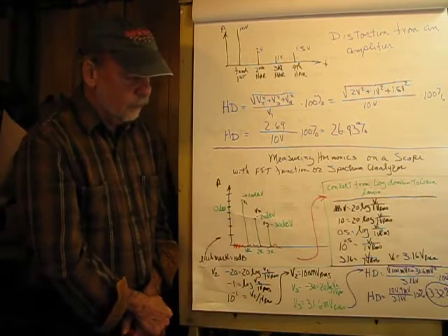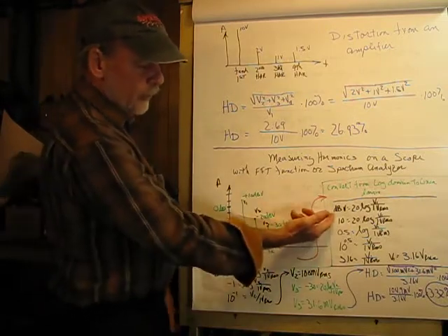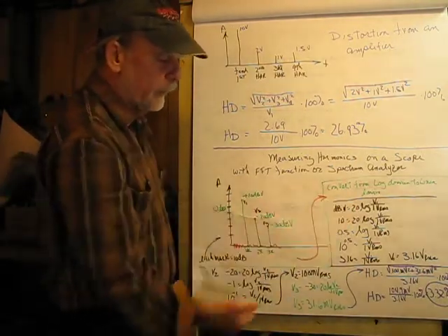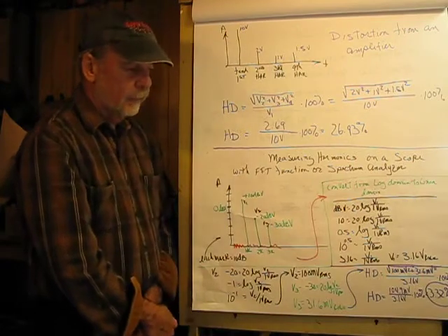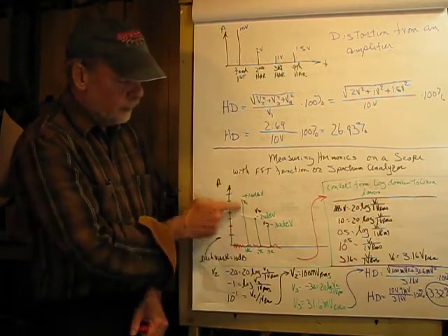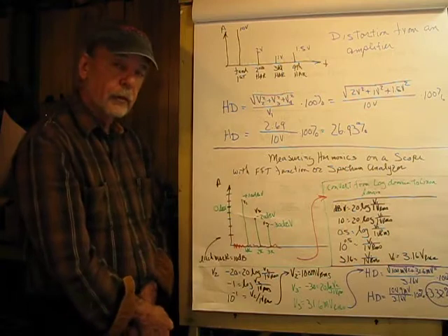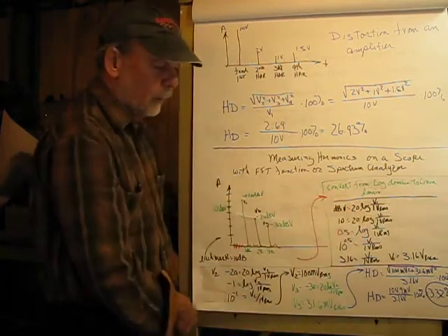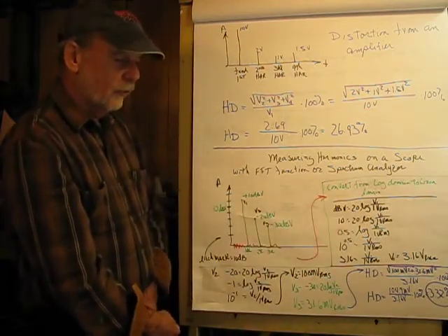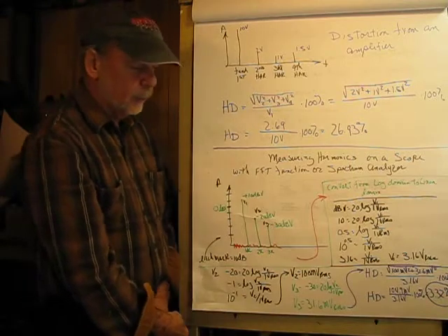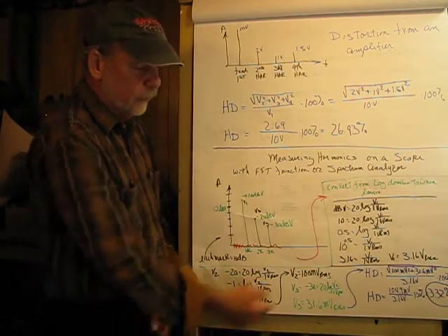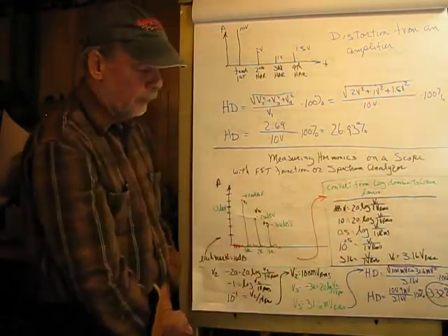So let's take our first guy here, and the general equation is dBV equals 20 times the log of V1, that's this guy, divided by our reference, which is 1 volt RMS. So we solve this the way we'd solve any decimal problem. We'll clear out the constant that's multiplying the log operator.